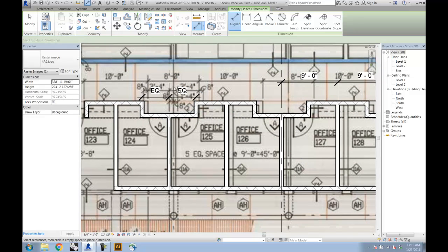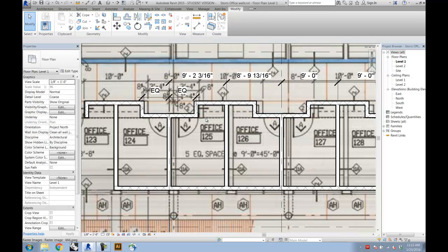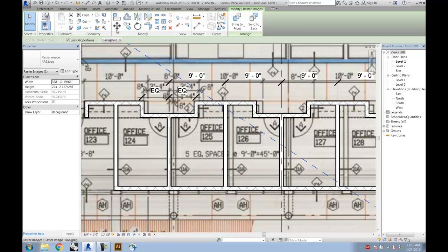And then one more time the measurement from the grid line to the center to this guy, and I can finish it, keep them all in alignment, select the wall that I want to move, and type in the dimension, 9 foot. Again, I could select the dimension if I want and lock it.